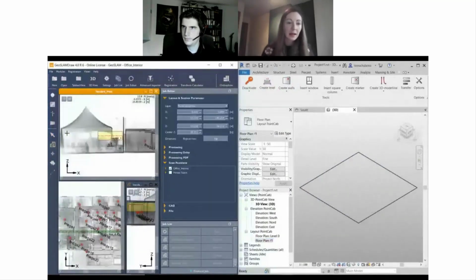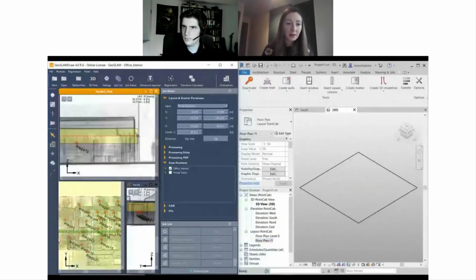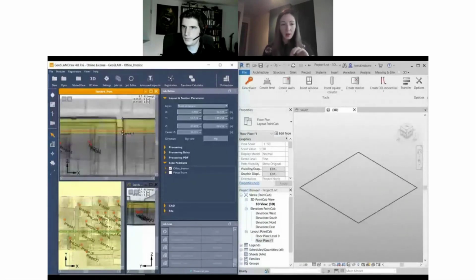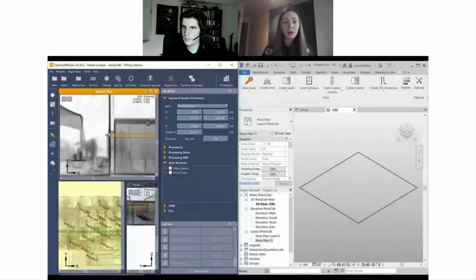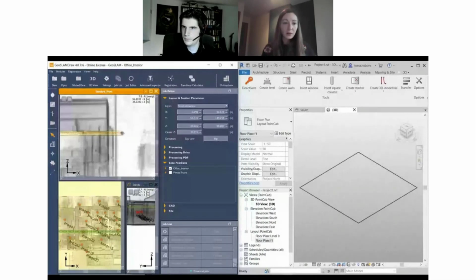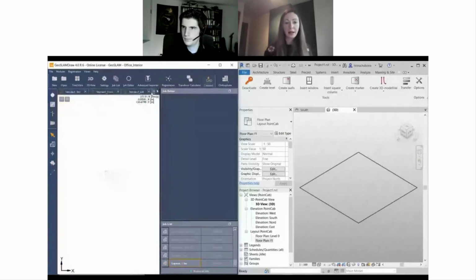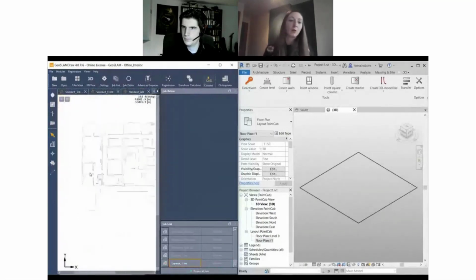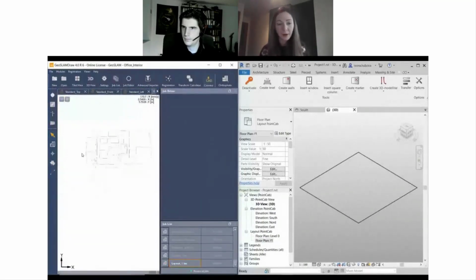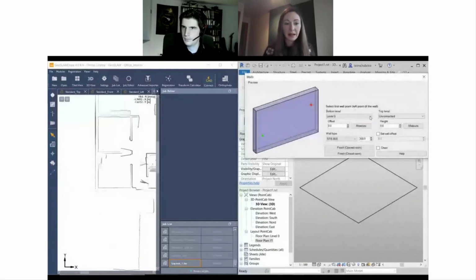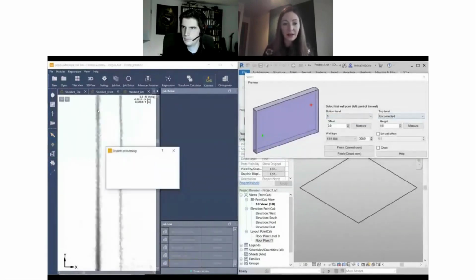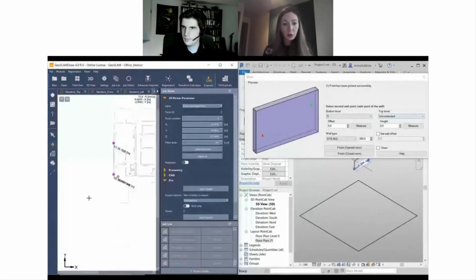And then you have the next tools moving from left to right, where you can generate the walls. And for that, I again did a layout through the building using a side view, where you can define the thickness of the layout and the image resolution for it. And I positioned it a little bit higher up to avoid the moving people and the furniture in this case. So I was looking for some clean section, which looks good enough.